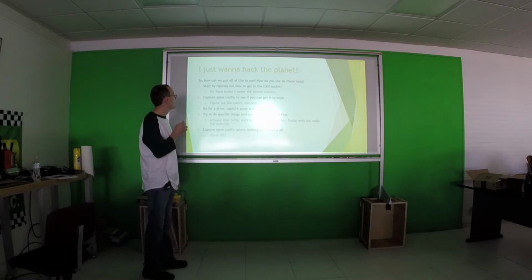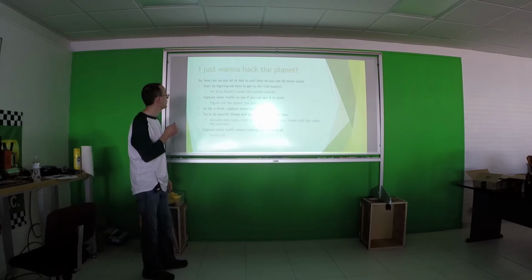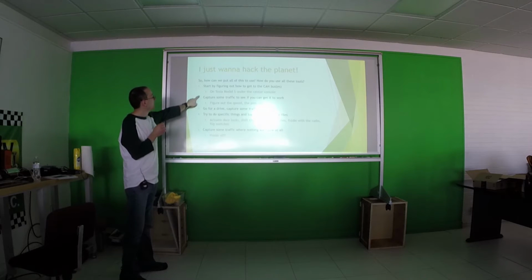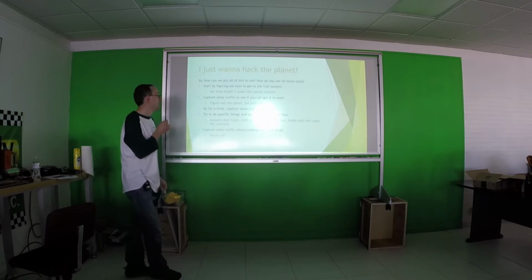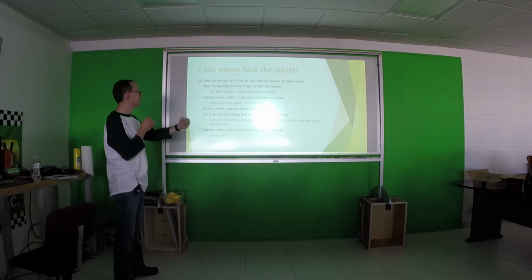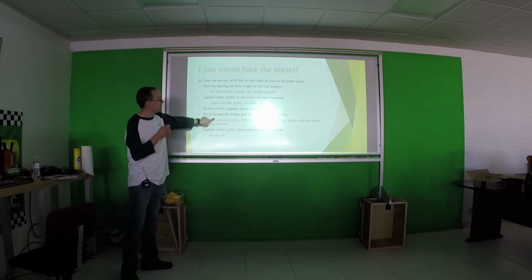And we had some reference for the speed. As Jack said, normally in a car the speed is going to be 250 kilohertz or 500 kilohertz. So you can pretty much guess, and if you try capturing some traffic, you'll see if you get any. The next thing to do is go for a drive and capture some general traffic. It's also nice to log separate files for the various things you want to figure out. Activate the door locks and save the file, shift the car from drive to park and save the file. Do various things and save them to different files so you have a reference of what changed. But the most important thing is to get some traffic where you didn't do anything, as a baseline of comparison.